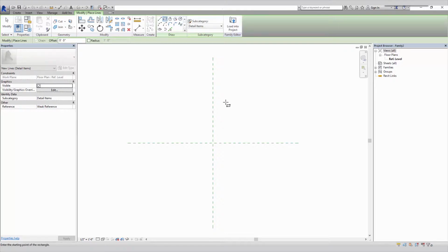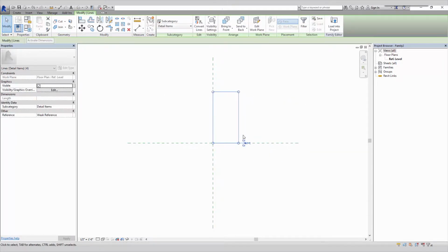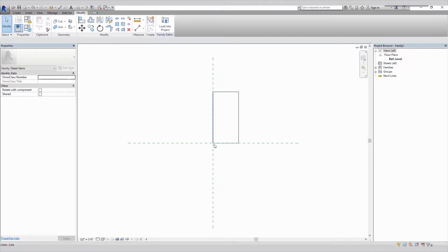I'm going to use the rectangle tool to create the shape. We want this to be 3, this to be 1.5, and we want this at the base. And this is important because as you bring this into your model, this intersection is where your mouse controls the placement of the detail. That also is relative to where, when you create a repeating detail, the next object goes.